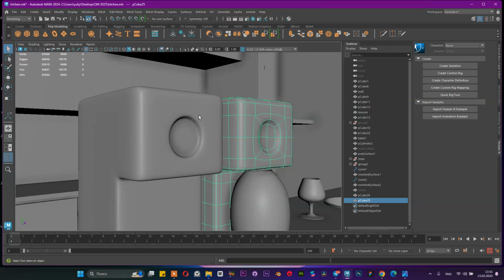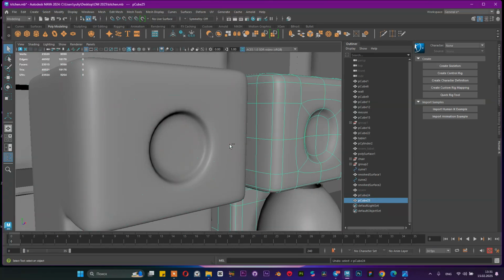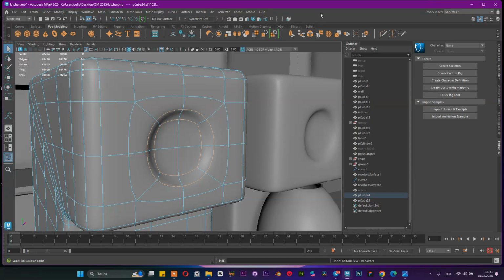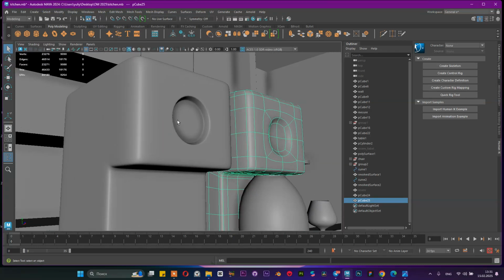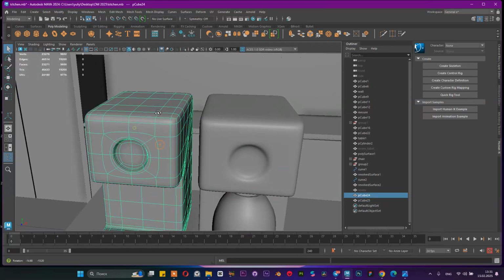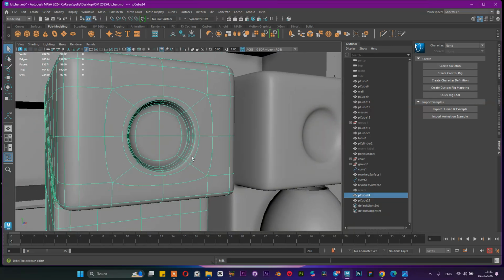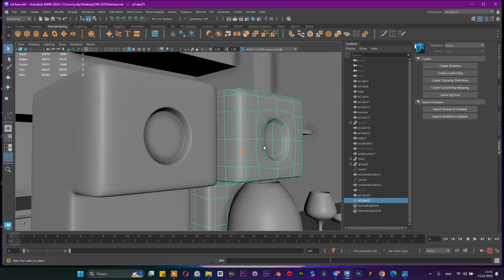If we just bevel, it's really accurate and smooth. If you want to make it sharper, let's undo and turn bevel chamfer off. Without chamfer, we have a really production quality hole here with many details. For example, when you start modeling hard surface, you are going to use this bevel without chamfers.